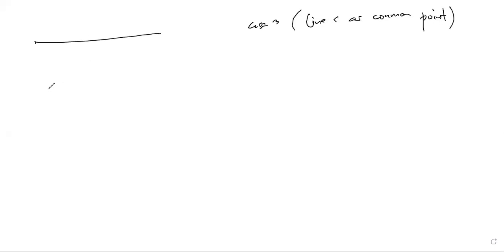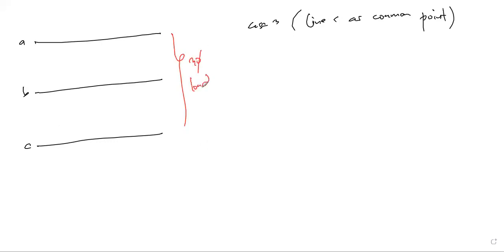So what is line 1, A, B, and C? This is A, this is B, this is C, assuming we have a three-phase load here. What we do next is connect the two wattmeters. So C is the common point, and obviously the current coils of the two wattmeters are in line A and the second one in line B.